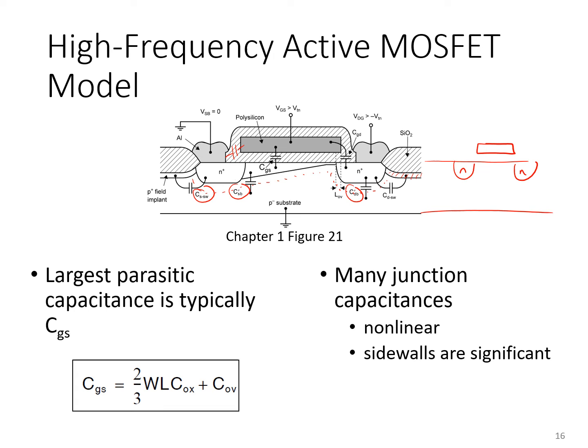Otherwise, you can imagine in principle, here you've got an N region and a P substrate. So you might say, well, all it would take is some large voltage to be applied on some wire running up here. And in principle, you might start to invert the channel region between this drain here and this drain here, between two transistors that are totally unrelated. So to prevent that from happening, a bunch of isolation measures are taken.